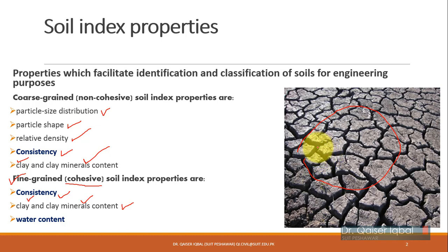Upon drying, this soil has developed a lot of cracks. So this is typically a property of montmorillonite, that it can change its volume a lot upon wetting and drying, which is usually problematic for your buildings, infrastructure, etc. If you change their moisture content, if you provide them with water, they will increase in volume, but if you dry them, their volume will reduce drastically, and that will result in settlement, shear strength loss, etc. There are a lot of problems caused by the volume changes, which we'll be discussing in detail in this course, in your coming course Geotechnical Engineering 2, and in foundation design as well.